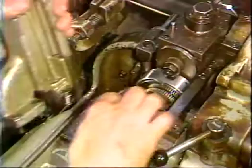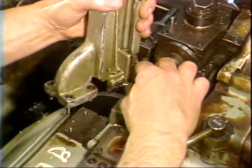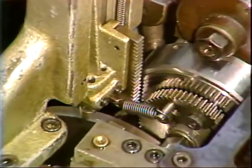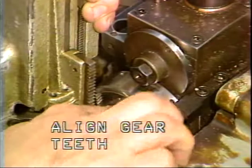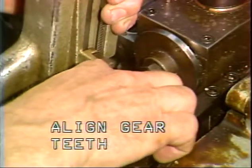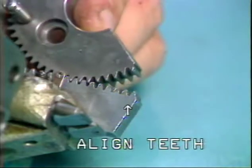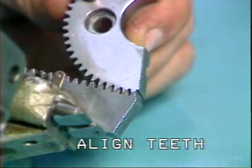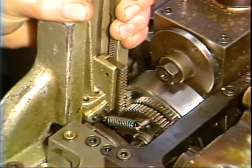This is the 1-to-1 attachment mounting base. The attachment is held in position by 4 mounting screws. Attach the return spring to the half-circle gear. Hold the return spring on the gear while you properly align the teeth of the rack and the half-circle gears. The teeth should mesh with the rack gear's last tooth outside of the half-circle gear's last tooth. Push the attachment down and install and tighten the 4 mounting screws.